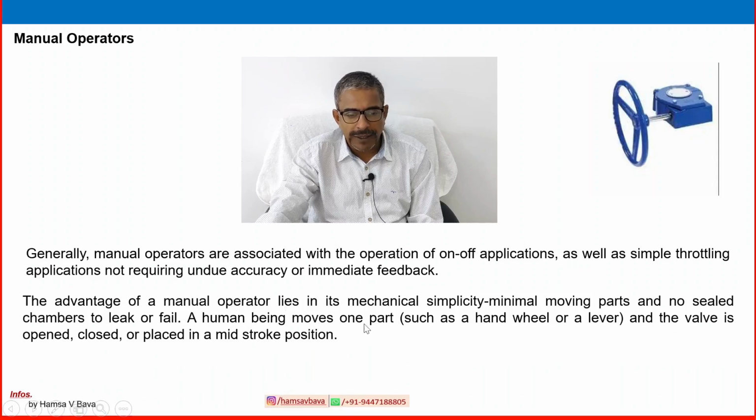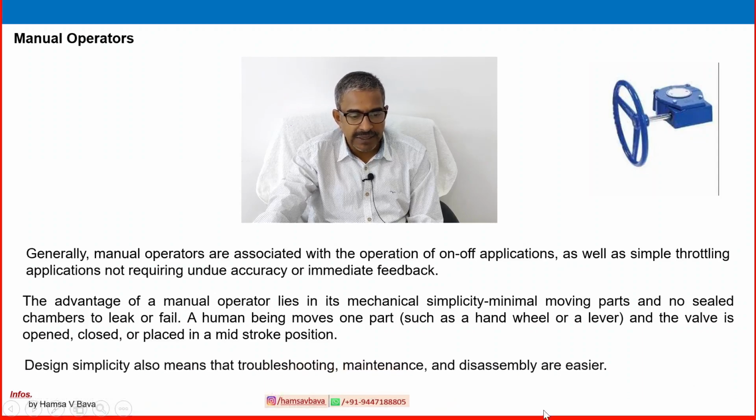The advantage of a manual operator lies in its mechanical simplicity, with minimal moving parts and no sealed chambers to leak or fail. A human being moves one part, such as a hand wheel or lever, and the valve is opened, closed or placed in a mid-stroke position. This is how the manual operation system works. Design simplicity also means troubleshooting, maintenance and disassembly are easier.